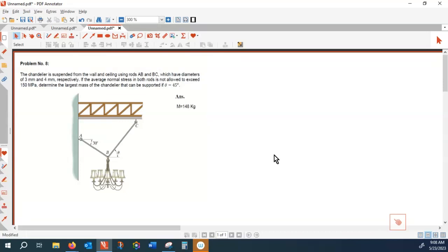In terms of sustainability, you don't want to use excessive material. Excessive material is when one of them is under stress, the other one is relaxed. But if both of them are under the same stress, that is the optimum design, because then you can control and put that stress below the limit. Every material has a limit. For this material, the limit is 150 megapascal. We don't want either of the cables to go above the 150 megapascal, but